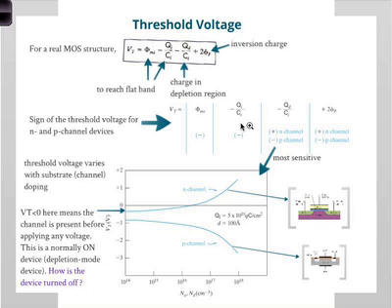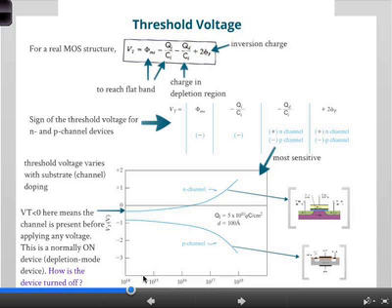The interface charges, you don't have any control because they're random defects, essentially. You try to minimize them as best as you can. This one, you have control because it is a depletion charge. You can control that by doping. It's directly related to the doping. This also you can control because these two are basically related to doping. So if you plot the threshold voltage, which is what you want to control, as a function of the doping concentration, because really that's all you have in your box of tricks to make devices, you can change the doping. Okay, this is what you get.